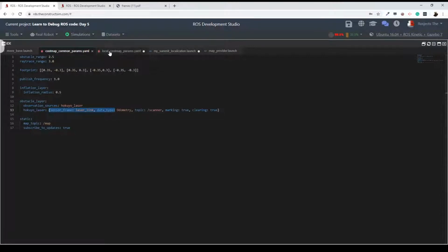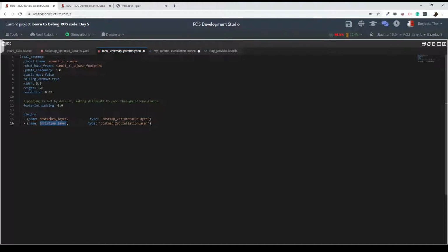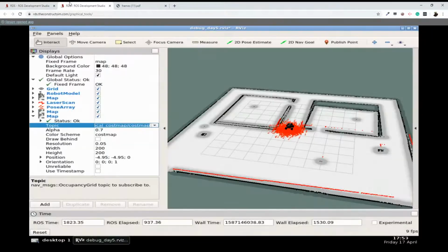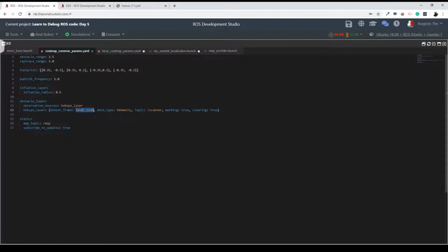Because the obstacles in the local costmap are going to be generated from the laser readings. The readings that the laser is getting all around are the data that is going to be used in order to build the local costmap. So I have to make sure that this data is proper, right?